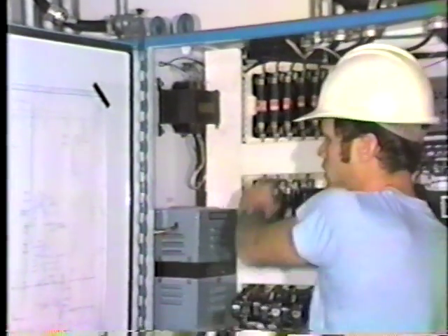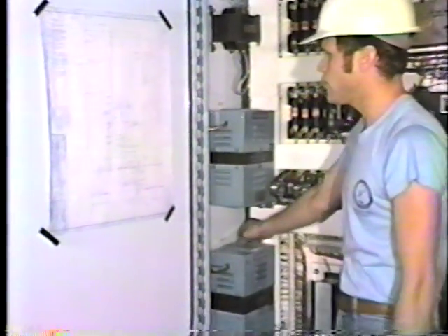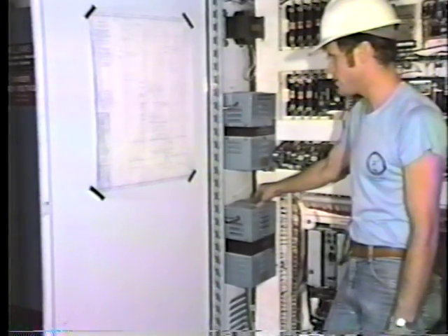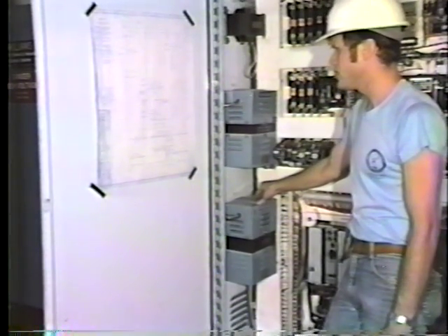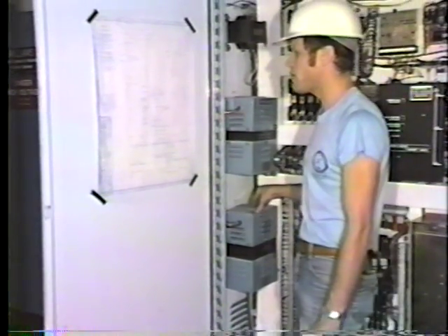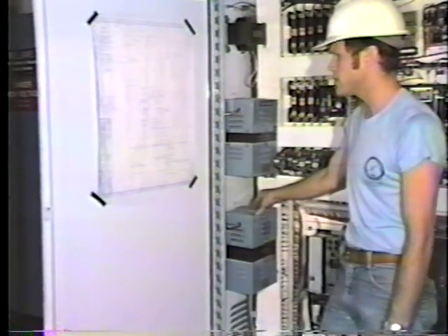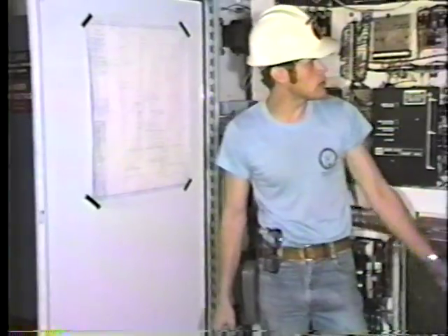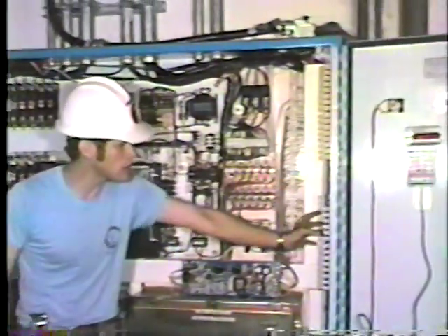Okay, hold up the red drawing. Where are F4 and F5 located, and what do they feed? They feed into transformer T4. And is that what you're holding? Yes. Alright, which feeds all our control power to our discrete inputs and outputs. Okay. Our discrete inputs and outputs are located on the side of the panel. Point to them, please.